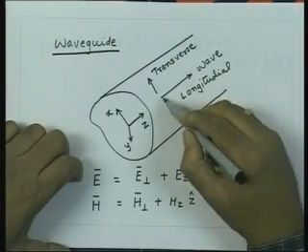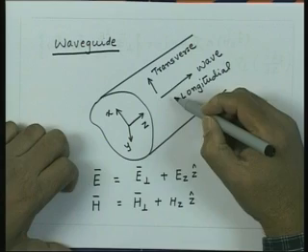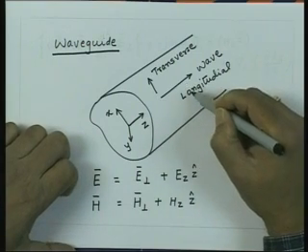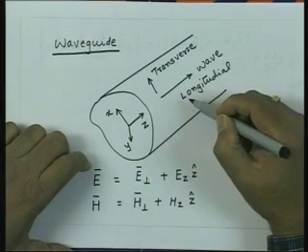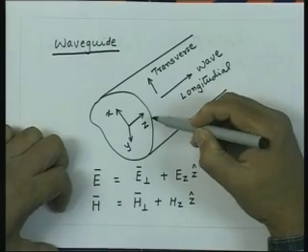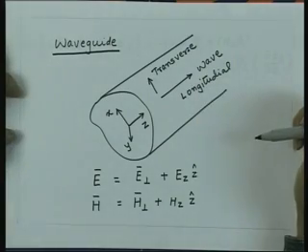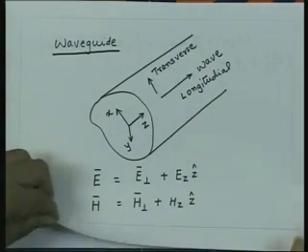Since this direction is the spatial direction in which the wave is propagating, generally we take the electric and magnetic field components in this direction, that is the longitudinal components, as independent components and try to express the transverse fields in terms of the longitudinal components. And precisely that is what we did.